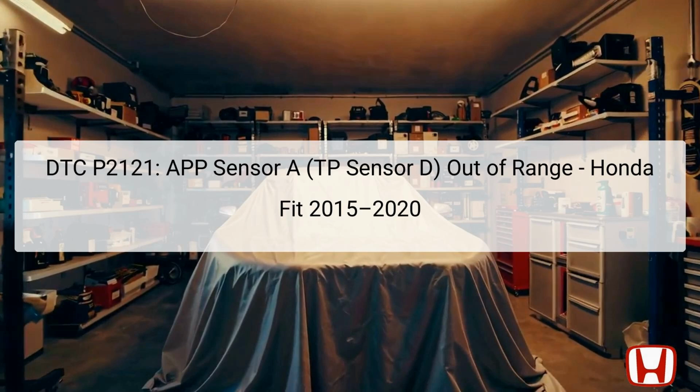Located within the accelerator pedal assembly, the APP sensor consists of a potentiometer that varies resistance based on pedal position. When the resistance varies beyond defined thresholds, it triggers the P2121 code, indicating a malfunction in the sensor's performance or wiring. Confirming this issue is paramount for ensuring the vehicle operates seamlessly and comprehensively monitoring engine dynamics.